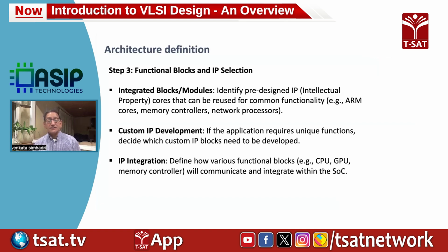Then some SoCs need custom IP blocks. I explained it earlier. For example, if the SoC is talking to a sensor, an image sensor, or some kind of sensor outside the chip, and if the signal is coming in the analog format, you might need an ADC to convert the data into digital format and process it.